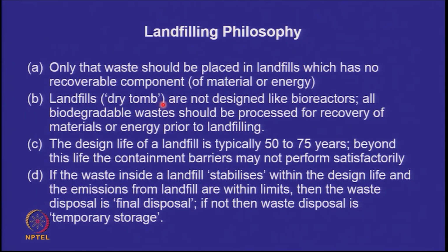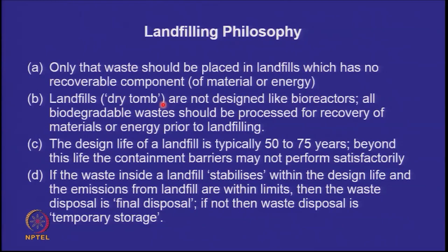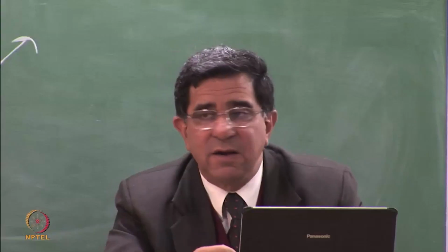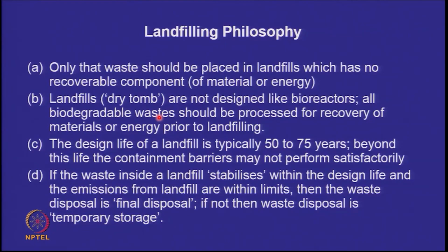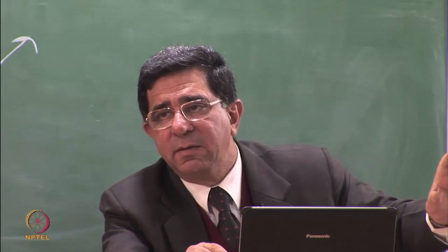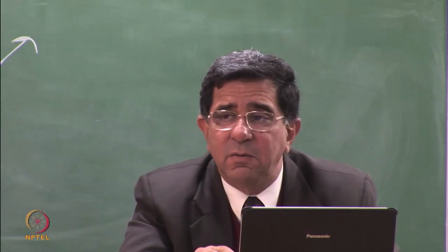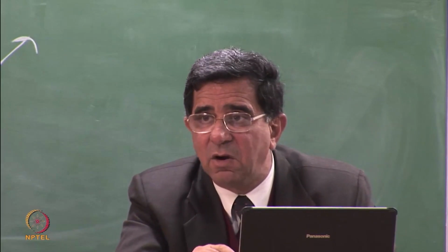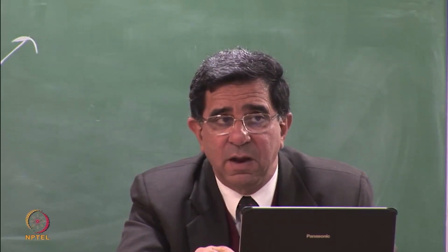These are impervious at the top, impervious at the bottom. These are called dry tomb. You don't allow any water to come inside it. So they are not designed like bioreactors. You'll hear of a term called bioreactor landfill, and we will discuss it in the next class. But you should remember that if you have a biodegradable waste, it should be sent separately to a biodegradable waste processing facility. The landfills that we are discussing here are dry tomb landfills, where all biodegradable waste which was reutilizable has gone to a composting or a biomethanization, an anaerobic or an aerobic composting plant.